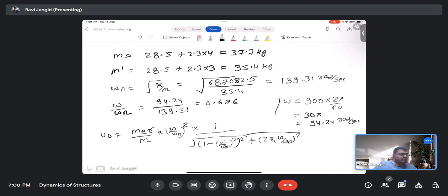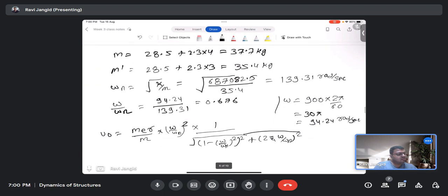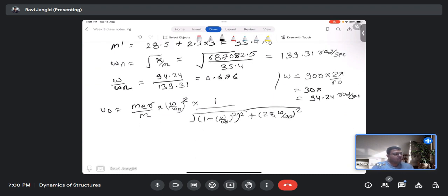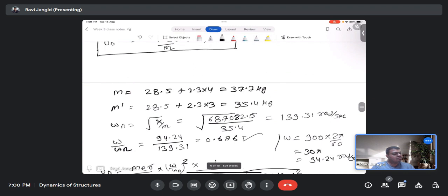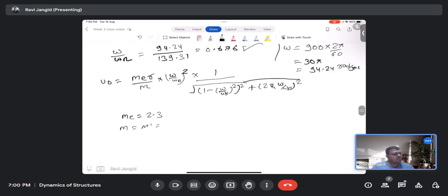Now you have everything. Omega by omega n in this one, m is 2.3. And your mass will be the updated mass, which is 35.4, which we have calculated, and the damping given is 5%. Find out what is u naught.